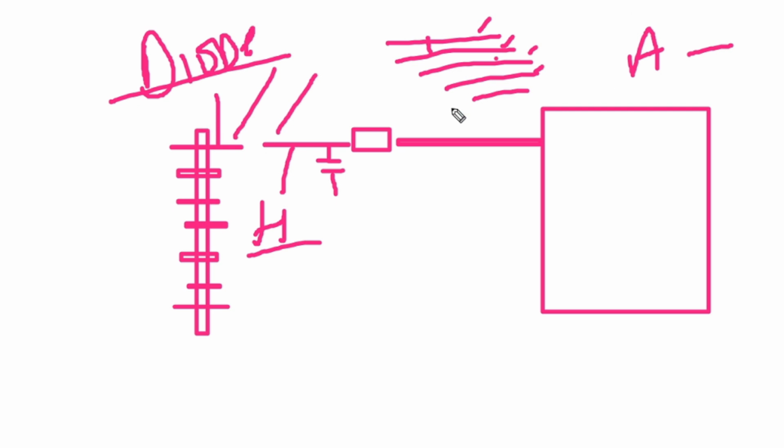That's why, with my experience, I tell you to open this resistance so you can confirm where the shorting is. If the shorting is on this line, just remove this resistance from this end. Both ends are open. From this end connected to the IC, if you measure a diode value here, you will see a good diode value, like 500.